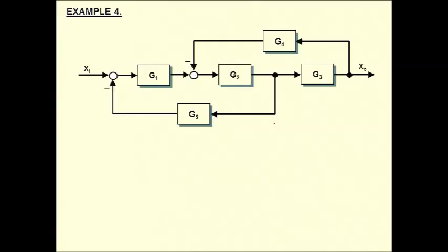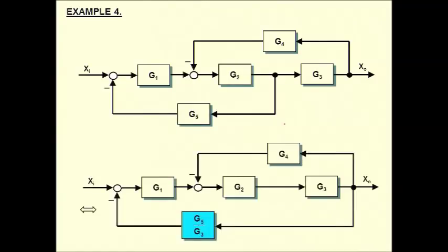So what do I do? I've got to use those more interesting rules about moving pickoff points in blocks or summing junctions in blocks. And that's what I've done here in this step. I'm moving this pickoff point behind this block in order to unravel this mess of feedback paths.